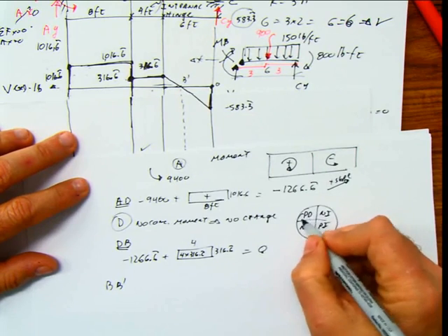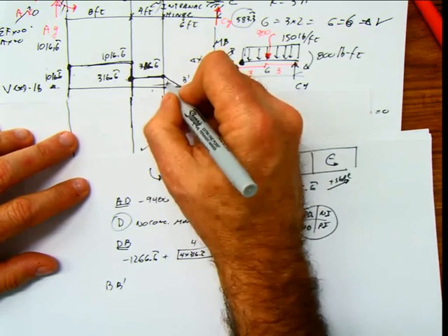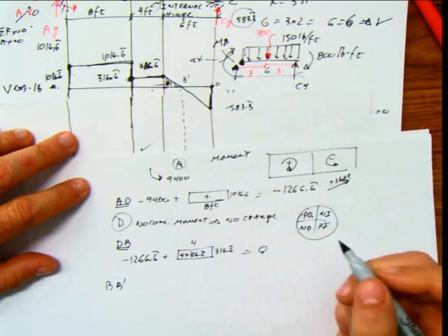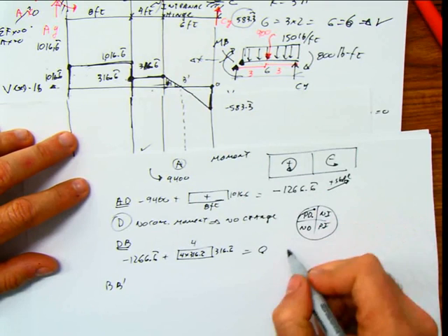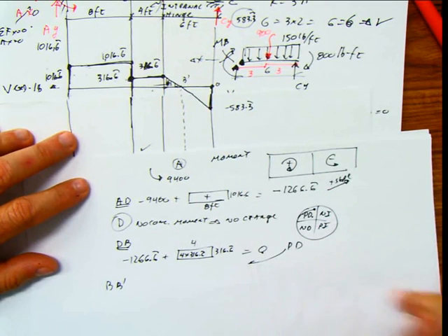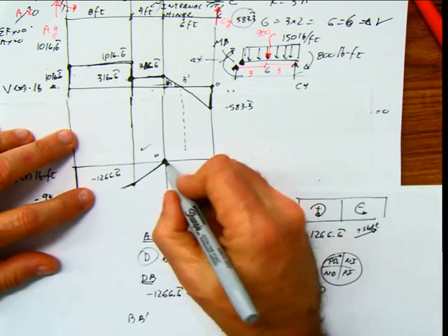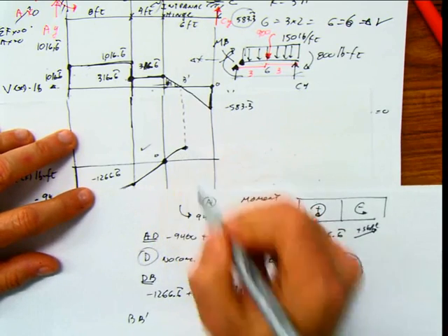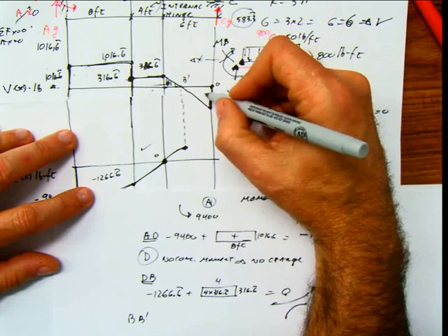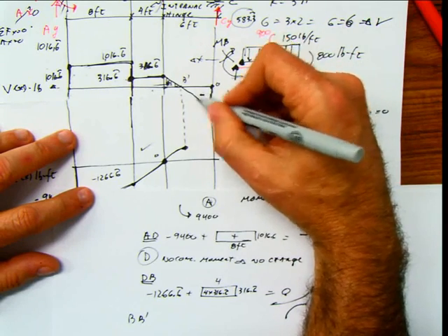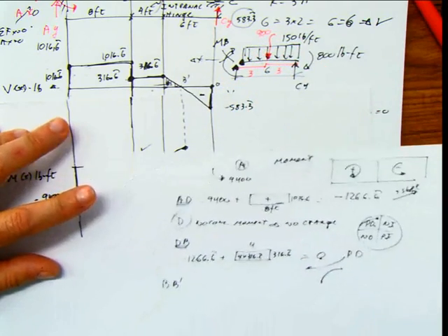So this is positive because it's plotted above the axis, and it's decreasing because the height of the shape is decreasing. Positive decreasing is something like that here. That means that my shape is going to be like that. That means that this value has to come up to this point. And then this is negative, right? And this is going to be negative increasing because the shape is increasing. And that will be B prime C.